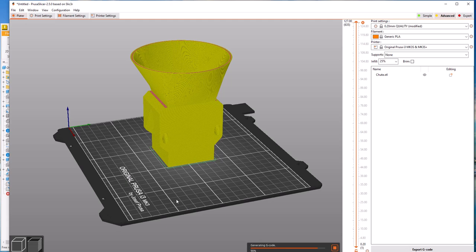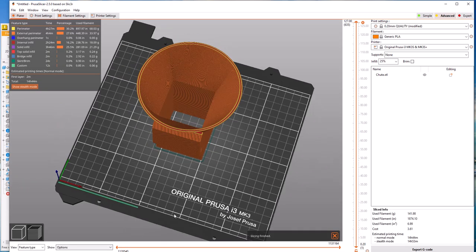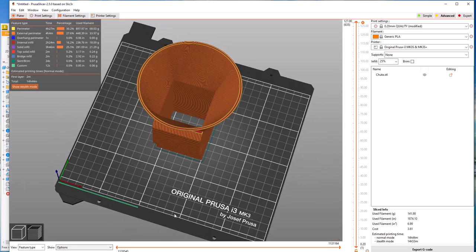I know this was a little bit longer video. We covered a bunch of different things in this particular video, so hopefully this helps you to improve your print qualities, improve strength of your parts, look at how you're designing those parts to be the right thicknesses, the right materials, maybe speeding up or slowing down prints as needed. Hopefully some of you play with the multicolor at some point when it makes sense. If you're going to be in the room for those changes, it's always a fun next step for simple prints is just to change the color, and so on.